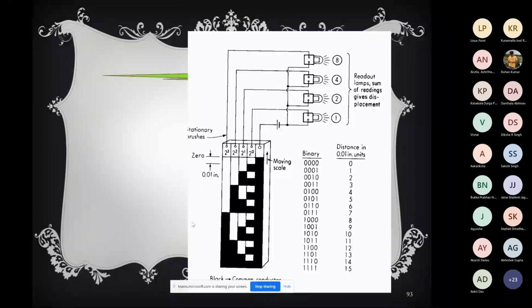The principle of operation of the linear optical absolute encoder is identical with that of the angular optical encoder. The only difference is that instead of angular motion, it has linear displacement, and the encoder is a linear rectangular shape made of transparent material instead of a disk. Using an etching process we can make dark and transparent parts. It is not a disk, and it will not rotate.